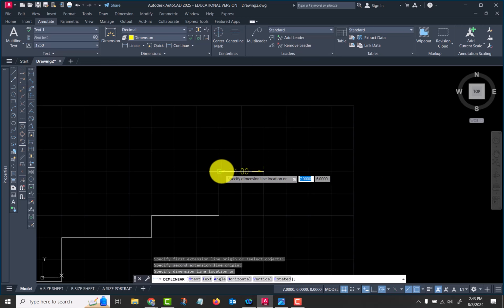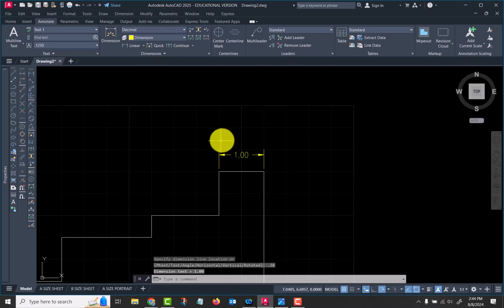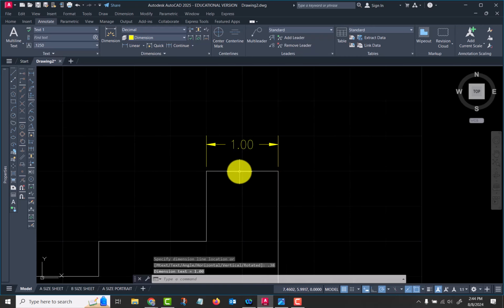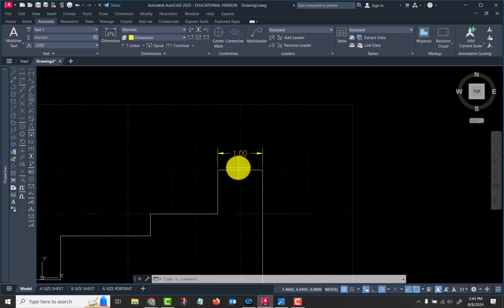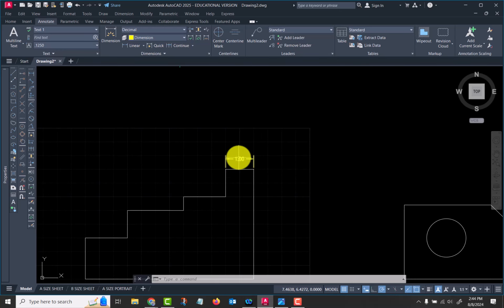if we come over to that corner and click, and then I pull straight up, and if I just type in 0.38 on the keyboard, it will space that 3/8 of an inch off of the object, from the last place that I click. Okay. And 3/8 of an inch is the normal distance for the first dimension line to be off of the object. And then each additional line, some books say a 1/4 of an inch, some books say 3/8 of an inch. Okay.